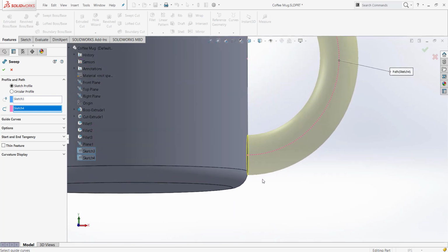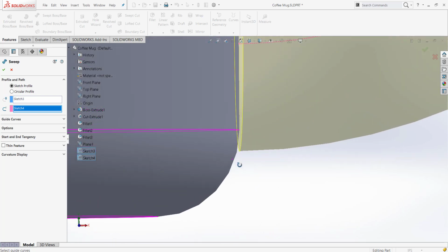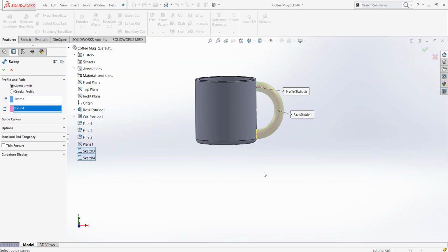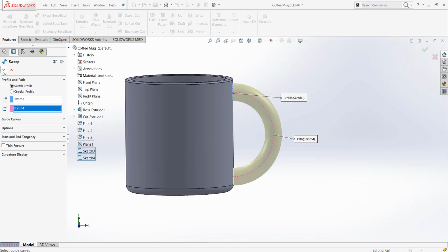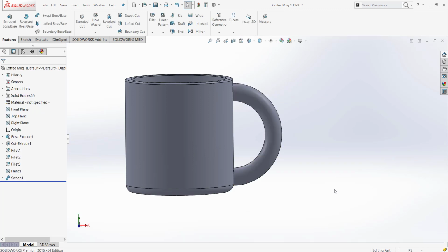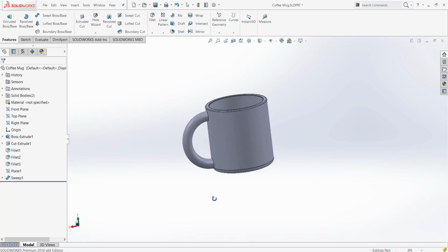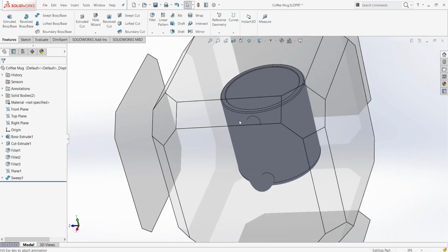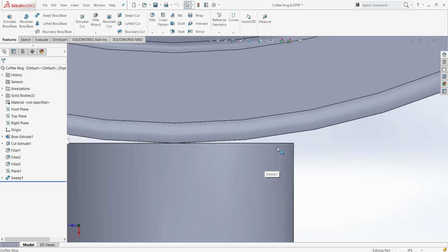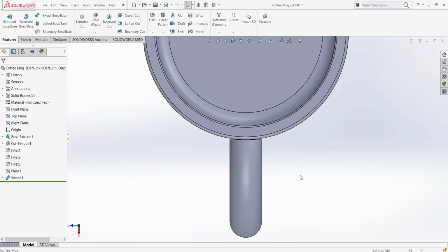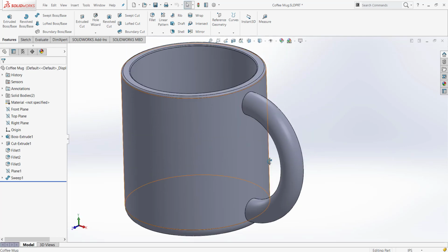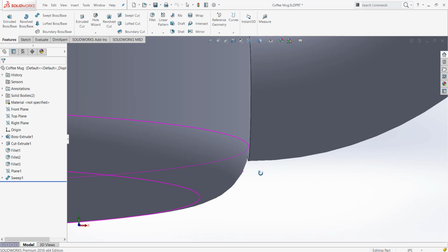And it seems like it looks okay, but when you get up close, you'd see that there are some gaps between both of these bodies. I'll click OK for now, just to see what it will look like. So it looks okay. Again, because this is on a tangent surface, you would see that these gaps would exist, and I'll show you later how to blend them. But first I want to get rid of this one right here.